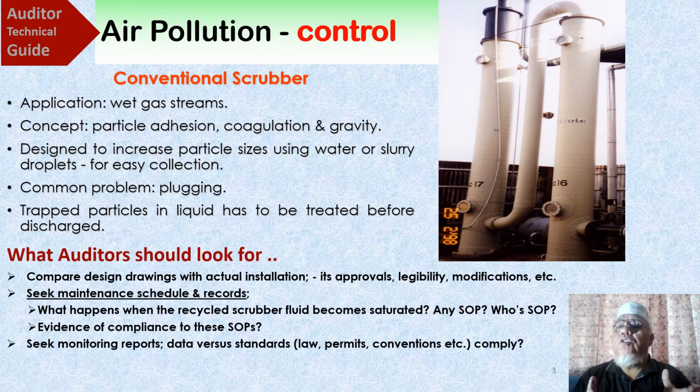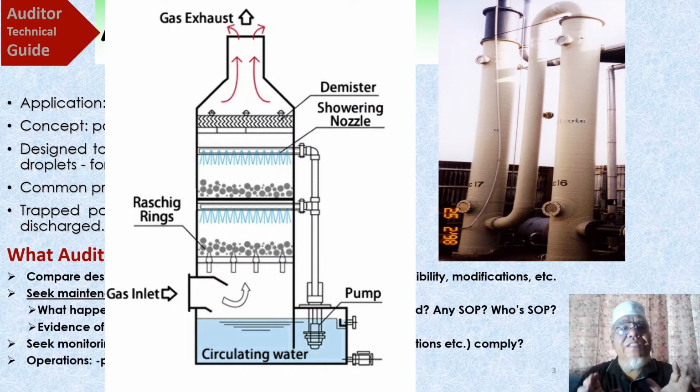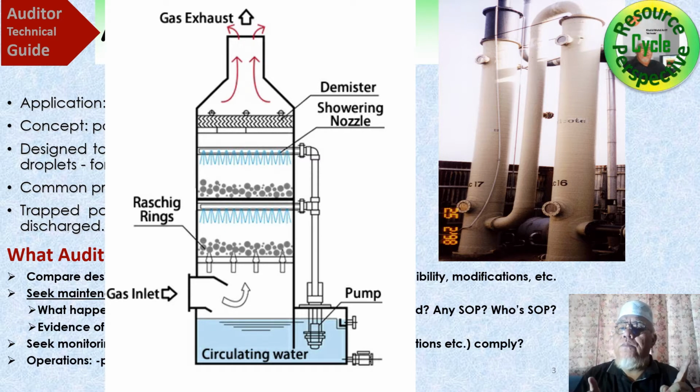The air pollutants, which are usually traveling along with the air, which is moist, so referred to as wet gas streams in this slide, are pushed to flow into an area or chamber already containing a particular type of moist which looks like mist or cloud, which awaits to receive contact and form bigger droplets.